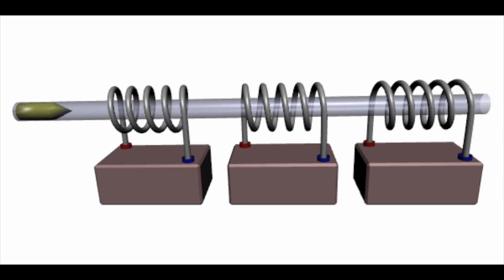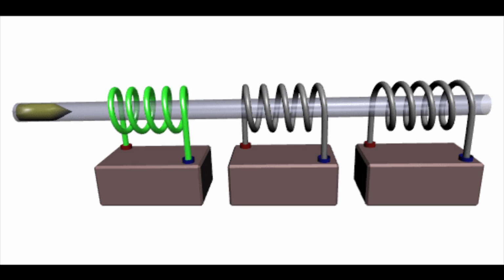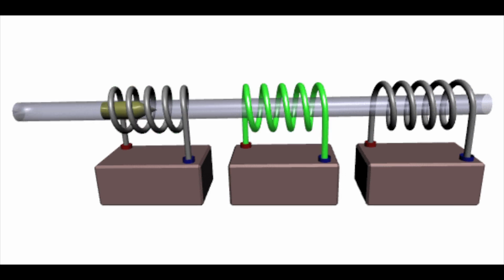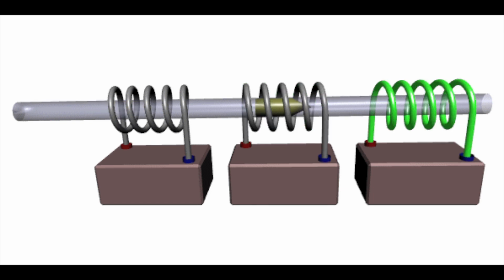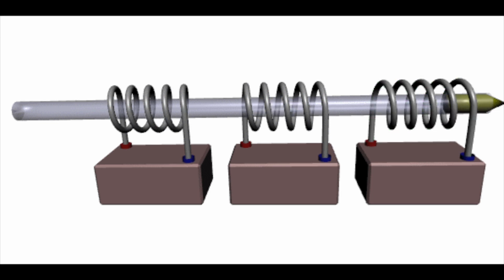A coil gun propels a ferromagnetic projectile by sequentially activating a series of electromagnetic coils arranged around the projectile's path. The projectile is pulled towards the center of each coil by the magnetic force of the wire's current. Immediately before the projectile reaches the center of each electromagnetic field, the coil's power is cut off, and the next coil in the series is given a current. This creates constant acceleration for the projectile and can reach extremely high velocities.